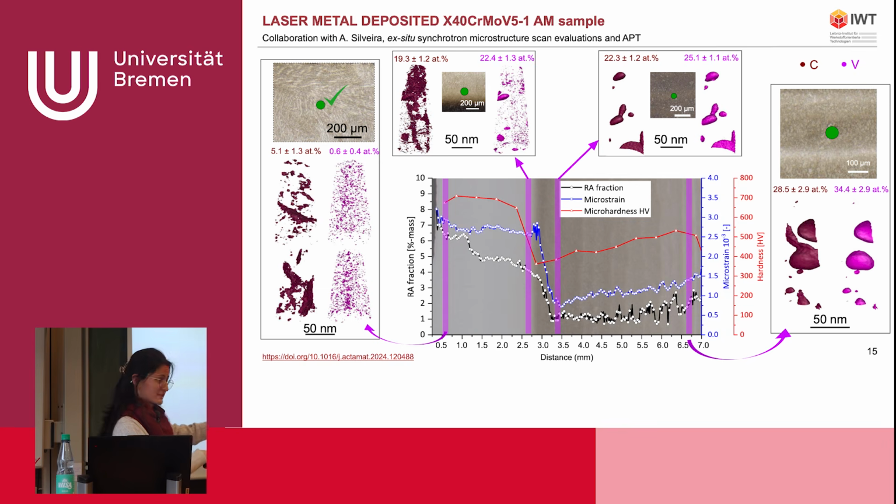So we have different regions here. Here is the quenched martensite, a very hard material that was directly quenched. Here we would have the accumulation of heat because of the heat coming from the layers above and the heat that would still be in the layer on the bottom. Here is a zone that is still tempered, but it has the substrate on the bottom that could evacuate the heat. That's why in the middle we have the severely tempered region. In all, we have three main regions here that we can easily see also with atom probe tomography.